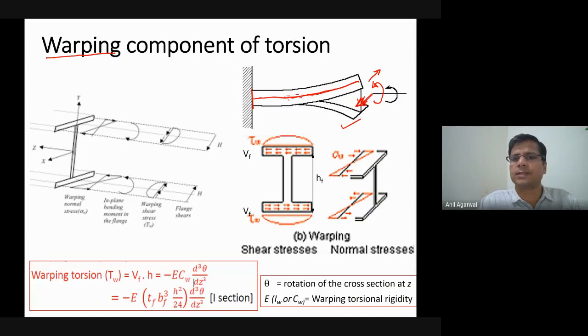Now, when you know that it is a bending problem, we know how the bending behavior of each flange is. So bending would basically require that the flange undergoes, with half of that flange undergoing tension and half of that flange undergoing compression.